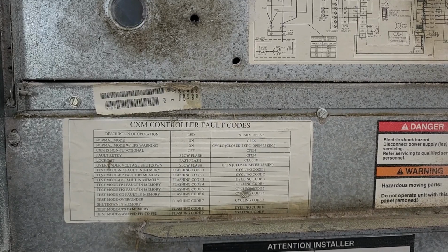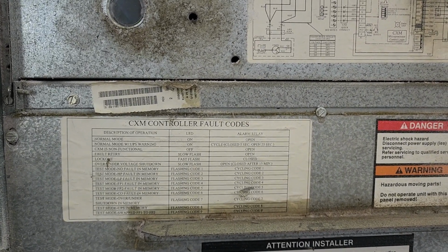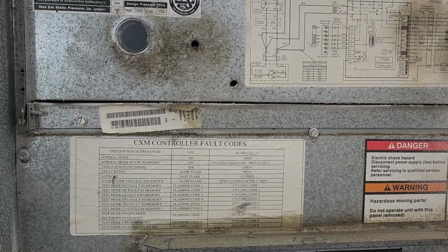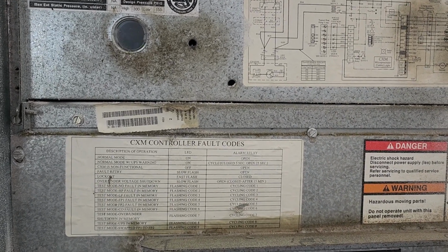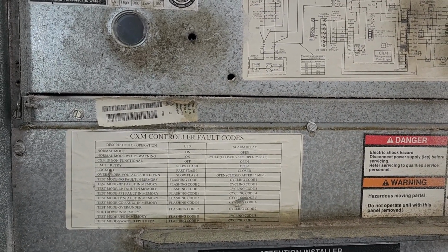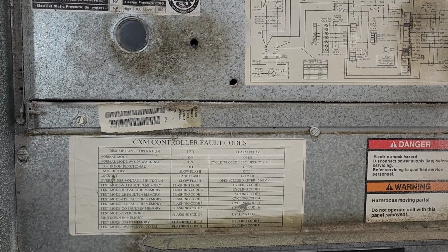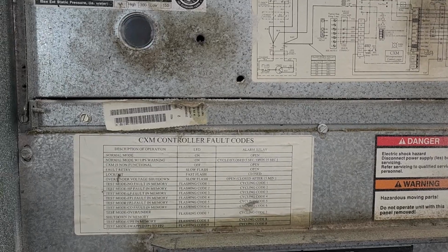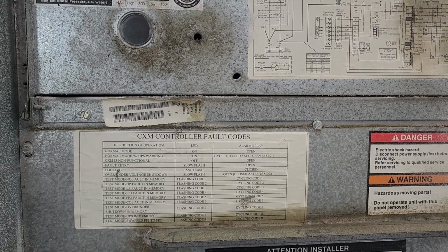Because if there is a short or a problem with the fan or excessive resistance, that could definitely be putting too much of a load on it, and the system just cannot provide the required power to turn the fan. So this is also some pretty useful information here, again, just from looking at a couple of things over a couple of minutes. So let's continue.